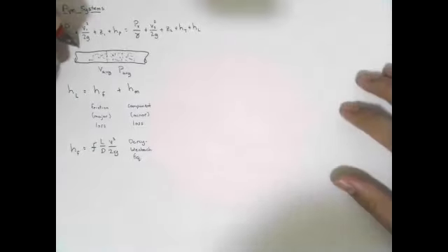This Darcy-Weisbach equation is a function of the length of your pipe and the diameter of the pipe. So if I were to write down my dimensions here, my length would represent the longitudinal length. And then diameter, of course, represents this dimension. And then the velocity head, v squared over 2g. And this is the velocity inside the pipe. So fluid flows inside the pipe with a velocity v.